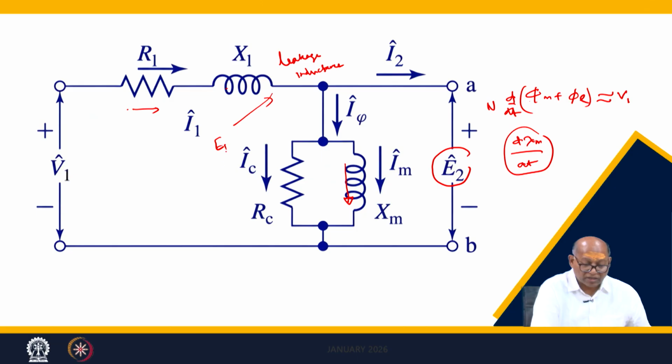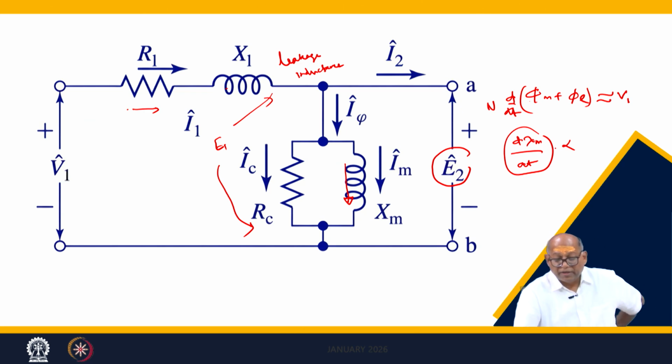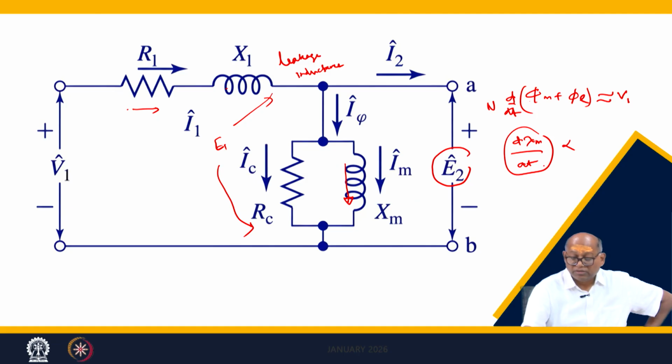This is E1. So, the same voltage, proportional to this, is induced in the stator. Depending upon the turns ratio of the rotor and stator, the voltage induced in the rotor is also proportional to this, multiplied by the slip. So, you can say that at the starting, E1 and E2, when transferred to the primary, just like a transformer, E1 is equal to E2. Then there is the resistive drop and leakage drop, and finally it becomes V1, just like a transformer.